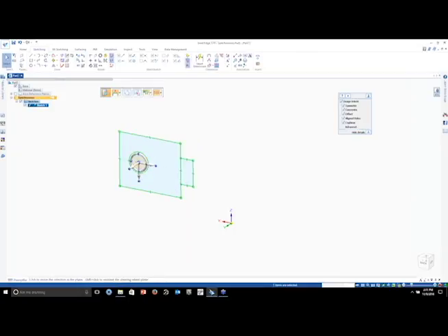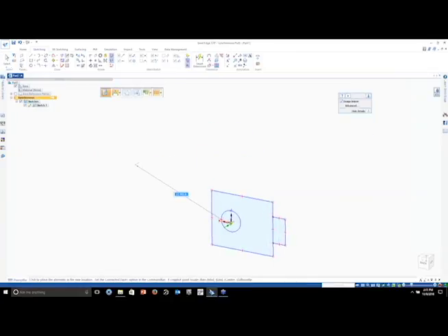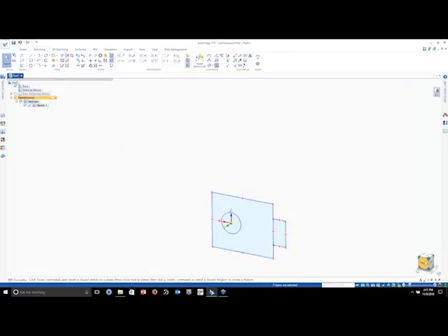So there's multiple ways to do that. I can kind of just grab it. And you notice I don't get anything to move it with. Because when you're in Synchronous, you get the little steering wheel to either add or remove geometry. If I pick my sketch from the Pathfinder, so I hit the little plus mark, expand it out, and grab my sketch, notice I get a steering wheel on it. Well, that's one way to move it.